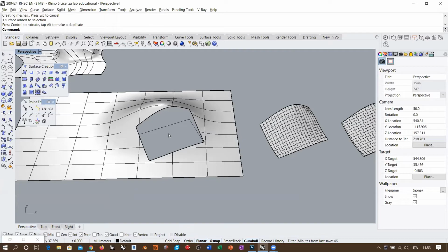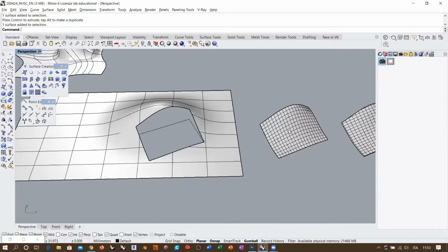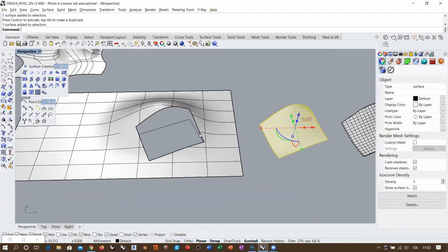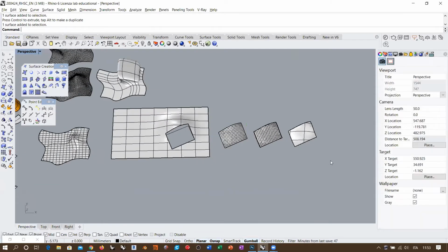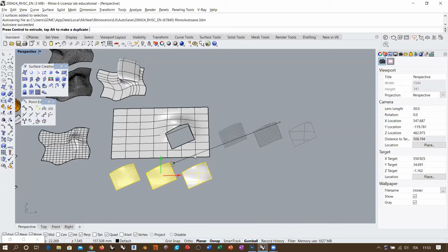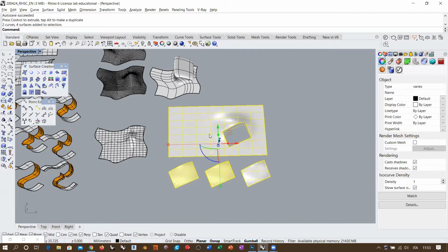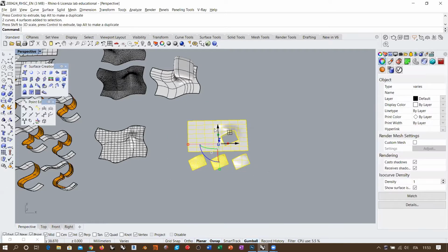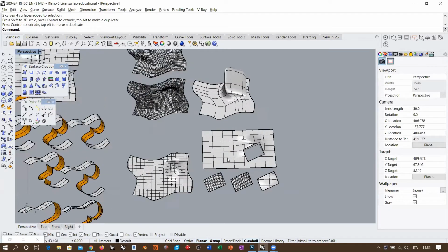Now, if you want this to be a perfectly smooth aerodynamic surface, you should also take into account that even the curvature control along the edges is producing some kind of sudden curvature variation, which is the jerk that we were discussing yesterday. Okay, in that case, from an aerodynamic point of view, this surface with this patch should not be exactly the perfect result. Okay, so you see that continuity problems become quite relevant when you work with these complex components, and it's very difficult to obtain perfect continuity.